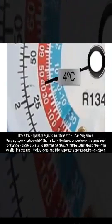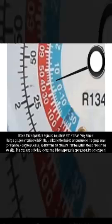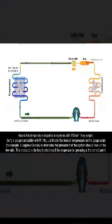Very simple. Using a gauge compatible with R134a, just locate the desired temperature on the gauge scale, for example, for 4 degrees Celsius, to determine the pressure that the system should have on the low side. This pressure is the key to checking if the evaporator is operating at the correct point.